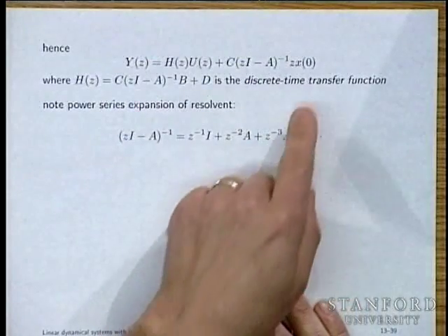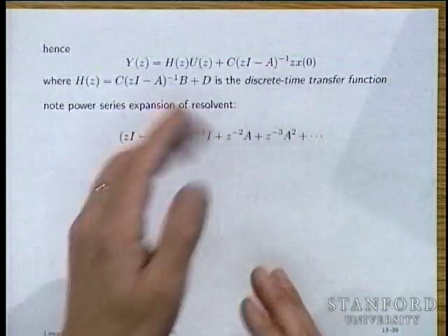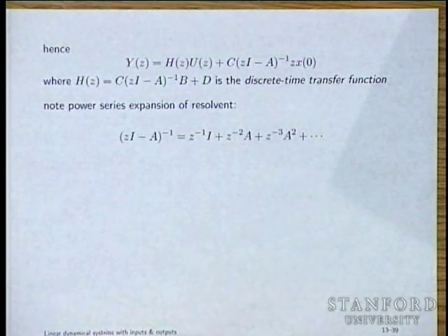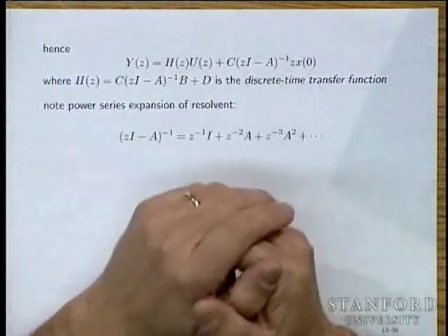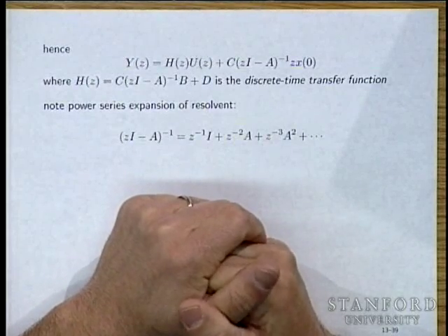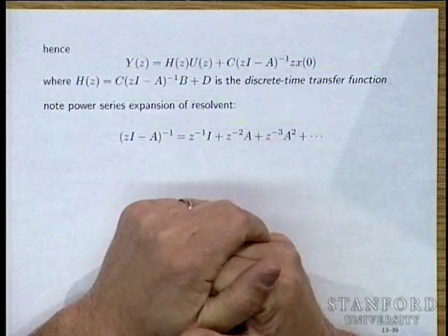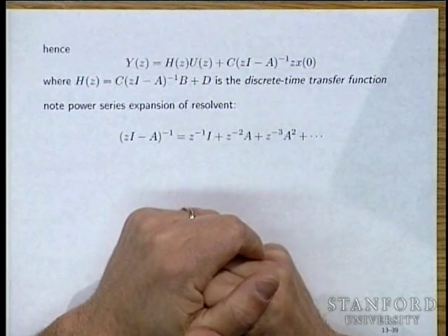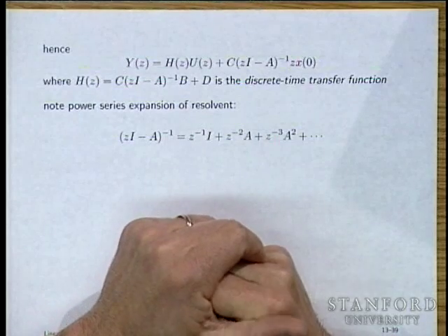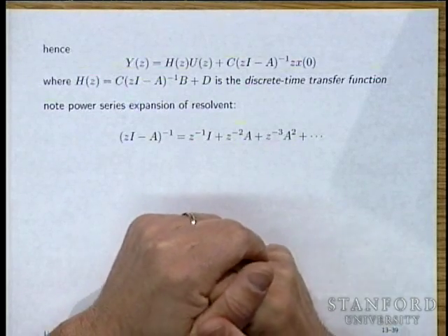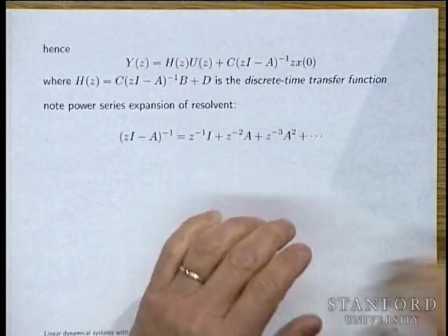If you sample faster and faster, the z has no effect because you're moving something over a smaller and smaller time interval. It would be like saying, no problem, I'm just using x at the end of the interval as opposed to the beginning. And as the interval gets small, the effect goes away. So that's not an argument as to why it should be there. It's an argument as to why it shouldn't bother us that it's there. That is just an additional argument, because the main argument why it shouldn't bother you is that it is correct. Which is a strong argument, not always completely persuasive, but that's it.